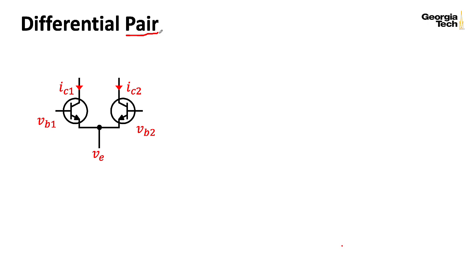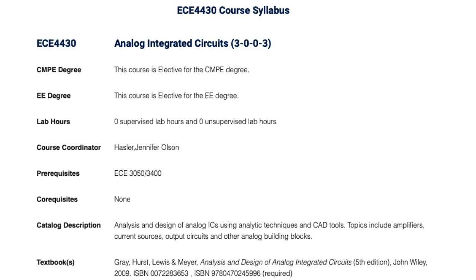If you're using discrete transistors that you've gone through a matching process for, like they used to do at places like Moog Music a long time ago, you'd want to put these close together on the PCB and sandwich them with some thermal compound to make sure they stay at the same temperature. This is a pretty standard trick in analog circuit design, particularly for analog integrated circuit design.